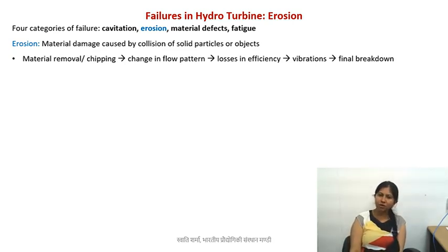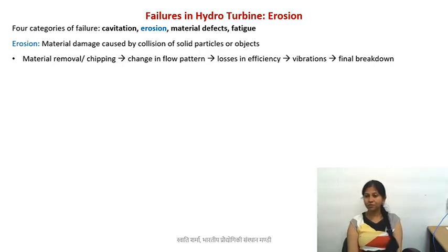However, we have talked about erosion also in the context of wind turbines. We have also talked about erosion in the context of gas turbines, where you have unburnt carbon particles that will hit the blades, and they'll also cause erosion. So erosion, not just for the turbine systems but also for a lot of other machinery, is one big problem, and we all understand it.